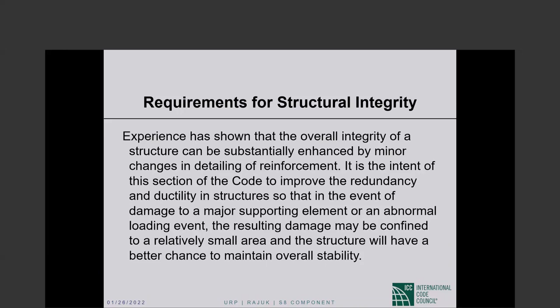Free end length is not something I understand. There is no free end. The upper part of the dowel is lapped with the upper column bars, and the lower part of the dowel is lapped with the lower column bars.